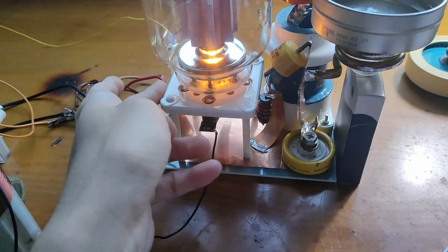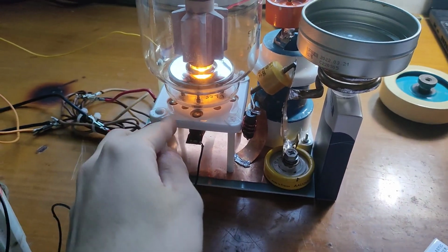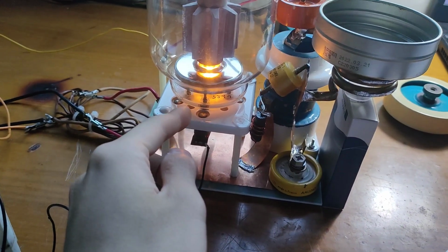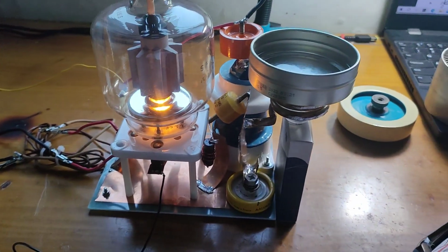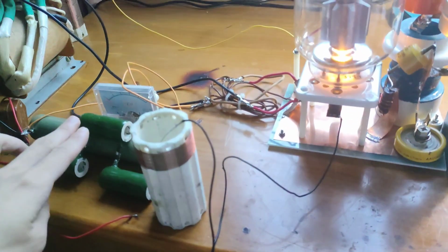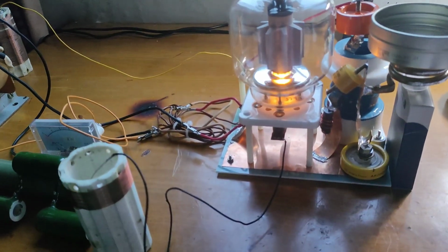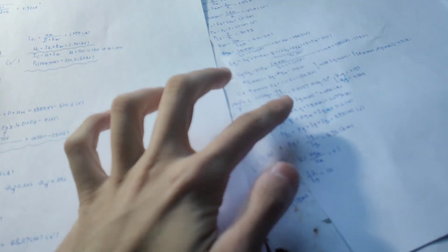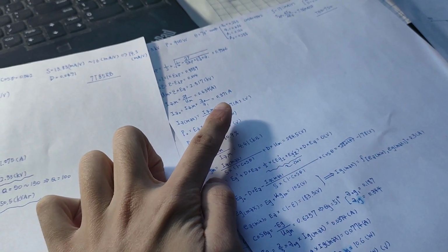The tube base is just slightly warm, which will be good because at the joint of the pane and the glass, the temperature cannot exceed 220 degrees. So what we just saw is that the system was drawing around 400 milliamps of current at 3 kilovolts, and the grid current is around 60 milliamps, which is a bit larger than we calculated here, right? Also, the cathode current is a bit larger.